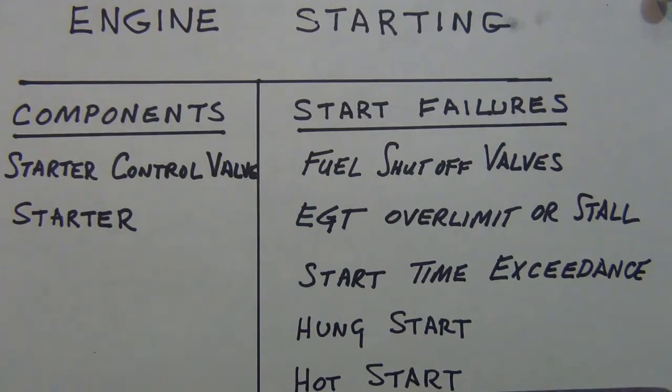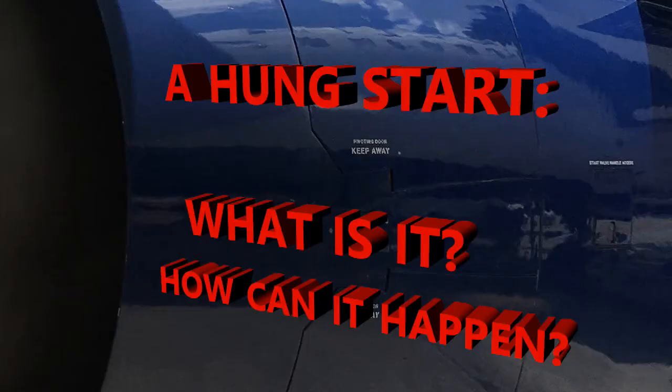That's a test question, by the way. Okay, so just know it's going to do 4 attempts, including the initial attempt, before it'll actually abort. Okay, that whole thing. It's going to shut off, the fuel shutoff valves are going to close, etc. So we don't want to have a problem with fuel still flowing. So, okay, that's what you know on that one, the information on the number of attempts.